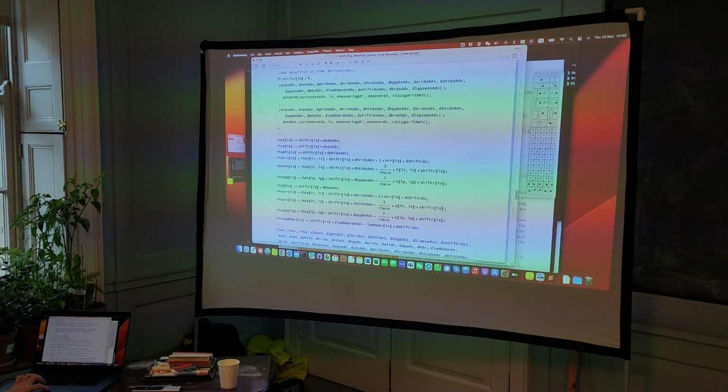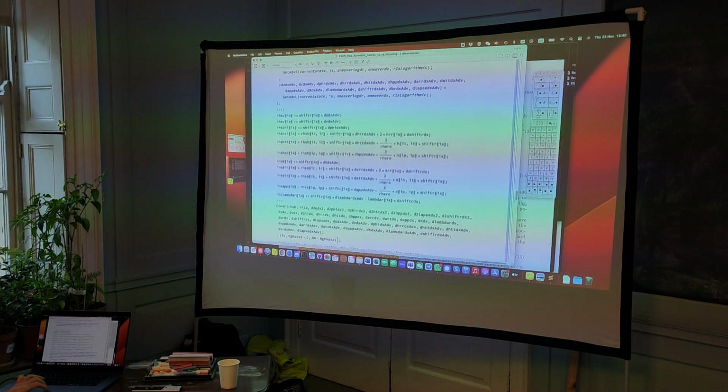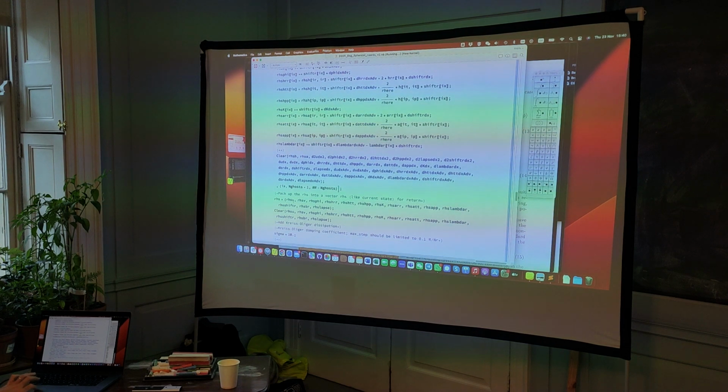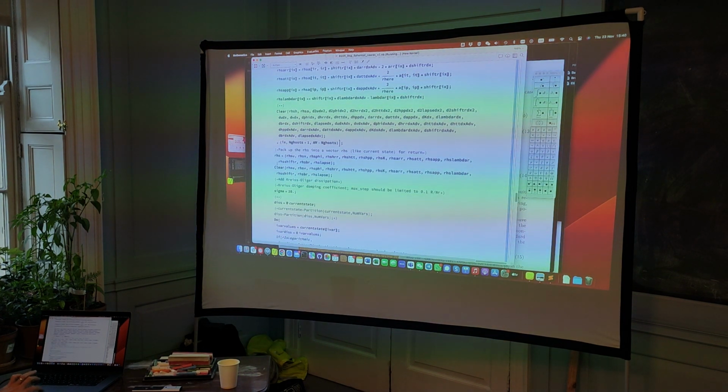Oh yeah, that's the advection term for the scalar field, I forgot about that. So we add the advection terms to all variables. And again, these factors that you see here are because we take care of the powers of r analytically. So that's why you pick up extra terms, but they just come from derivatives of the powers of r. You can just work this out analytically. And you can see we only do this for the points which are in the physical grid. And once we've done that, we group all these into a single vector, which we call right-hand side. And then once we have these, we can use the standard RK4 type algorithm to step forward in time.